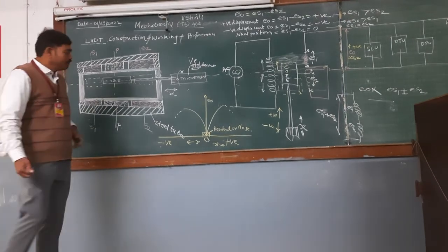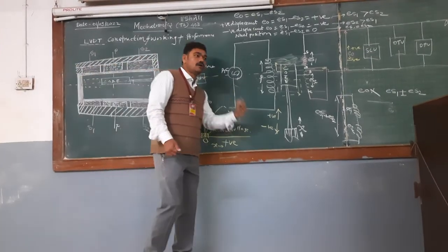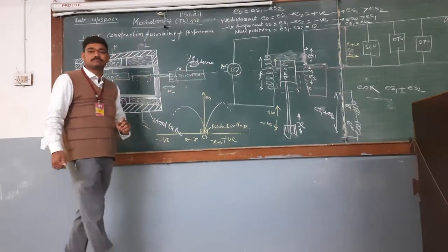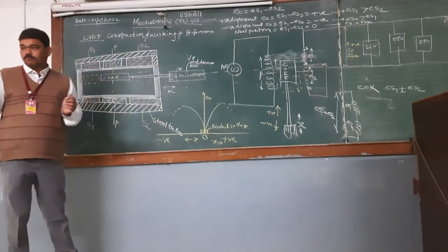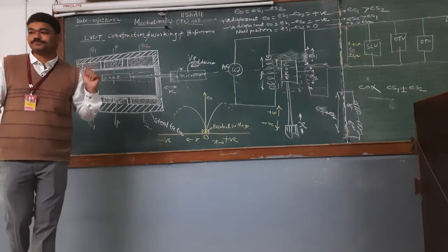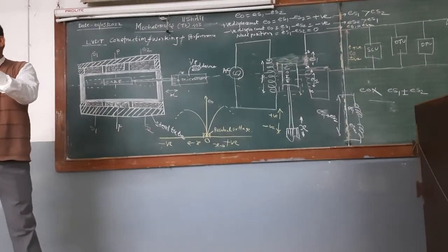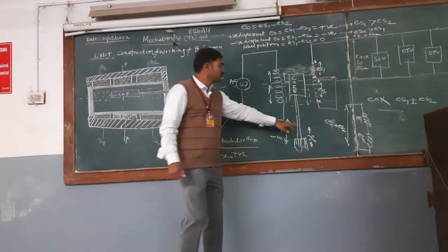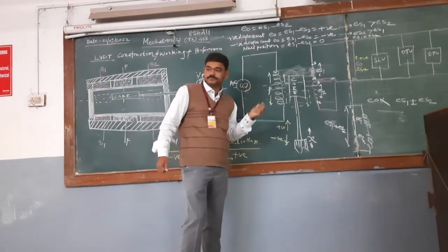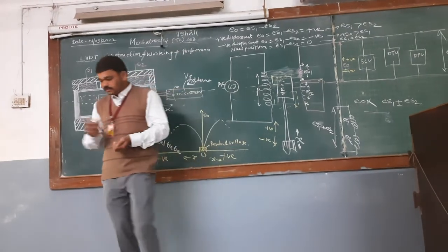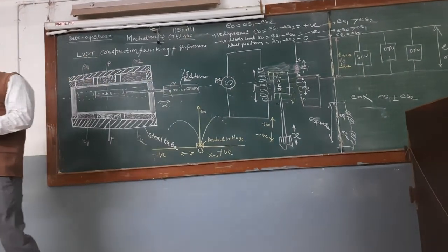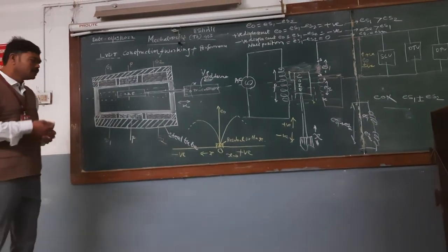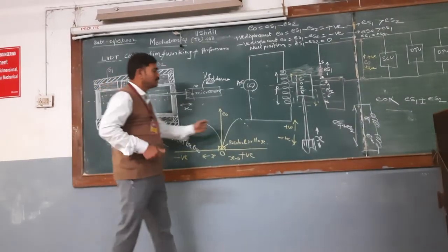Okay? And wherever a very small amount of displacement is caused by some physical parameter, to measure that displacement, LVDT is used. For example, beam deflection, which is very, very small. To measure it, just attach the core output to the LVDT, and it will measure it. There are 1,000 applications for LVDT.